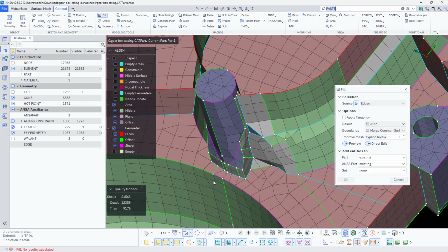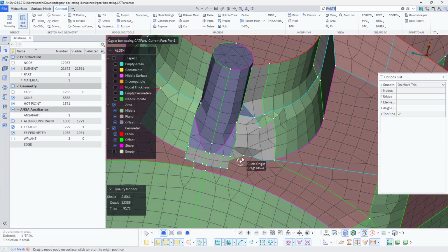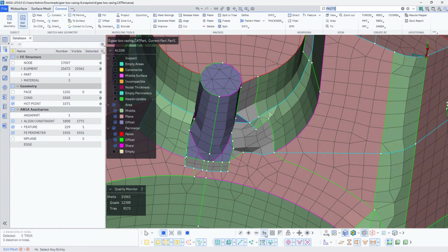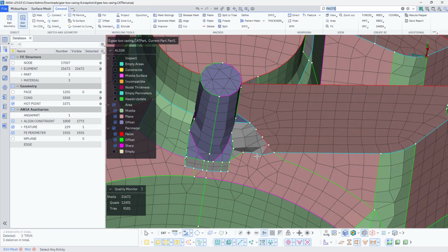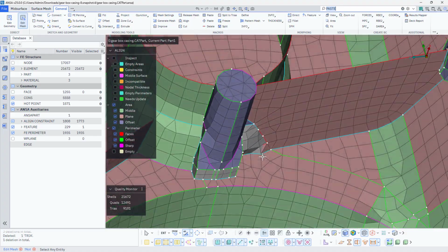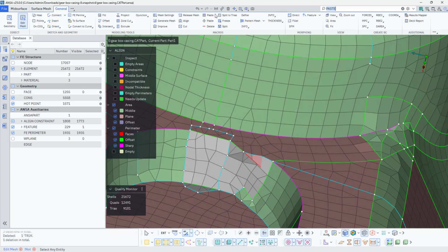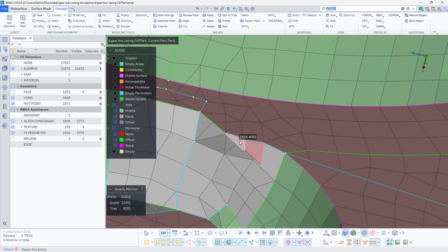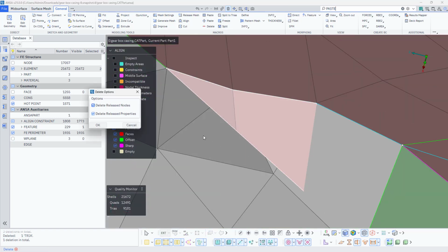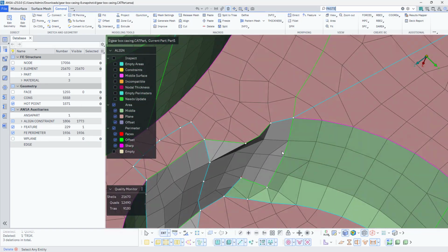Yep, so this is fine at the moment. So here I think you can bring back your rib and just check how it is dealing here. Rib is going inside, so let me just delete the rib, and then this should be straight.